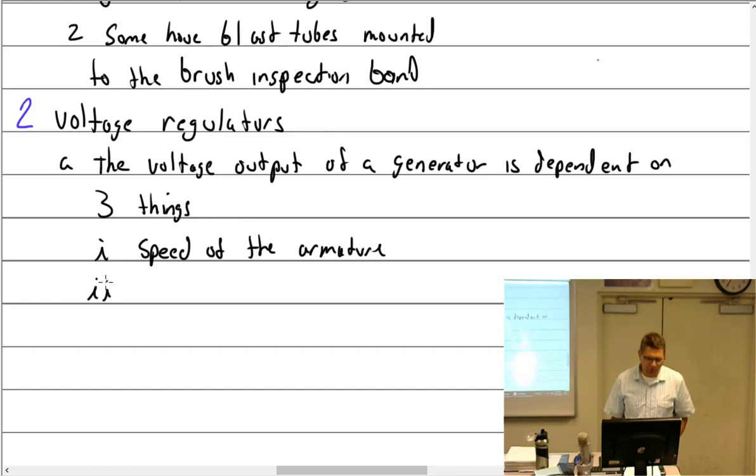All right, so I told you when flying the Cessna 140 at night, they had a little 20 amp or less generator, has a landing light and a taxi light on it, and the nav lights, and that's about it. It works just fine when you're flying along, and then you pull the power back to land, you go back to an idle, and what did I say happens? Generator just shuts off. It's just offline. That's the way they work. It was not broken. The faster you spin it, the more the armature is cutting the lines of flux. The faster it's rotating, you have a greater change, and so you get more output. So it's dependent upon the speed.